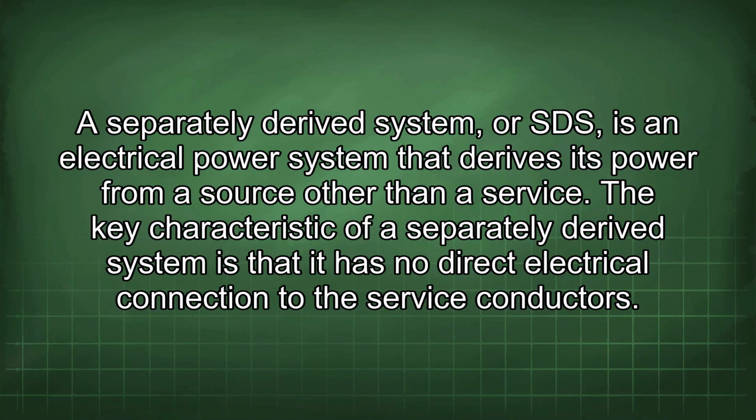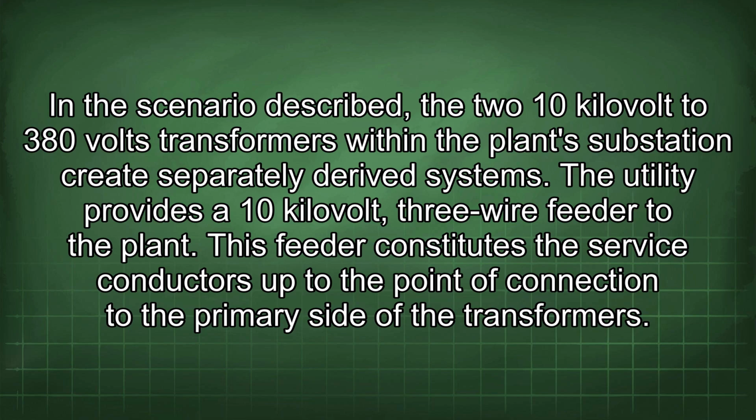A separately derived system, or SDS, is an electrical power system that derives its power from a source other than a service. The key characteristic of a separately derived system is that it has no direct electrical connection to the service conductors.